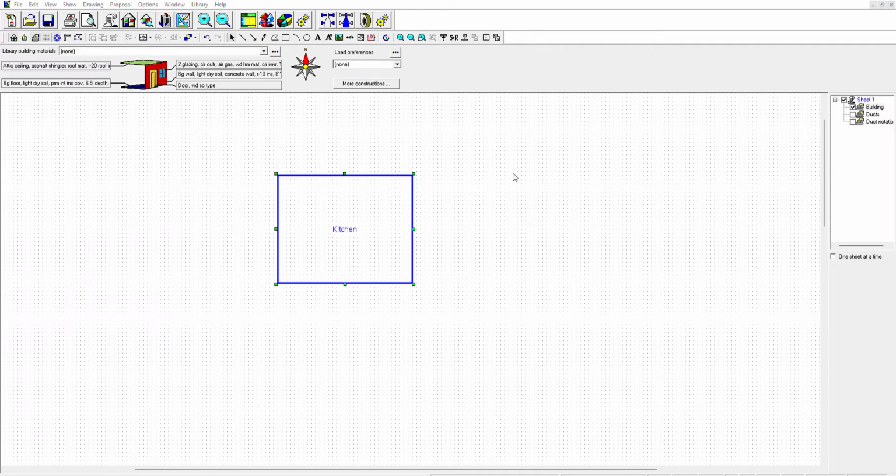Okay, now the duct heat loss factor depends on where the ductwork is. So this isn't going to be in the conditioned space, for example, but if the ductwork is in the attic, we're going to put in here vented attic and then return vented attic, but let's leave it in conditioned space for now. Then all of this is going to be 0 based on this duct loss factor, and then automatic branches, this is mainly for duct design. Okay, and the other ones are pretty much extra data.